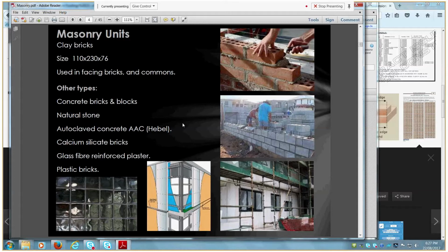It's also an important consideration for even some sheet metal products for your walling. Some of the flat pan, high ribbed profiles require that you have your windows joining partway through the flat pan and not at the ribs. So it's an important consideration for all types of cladding.